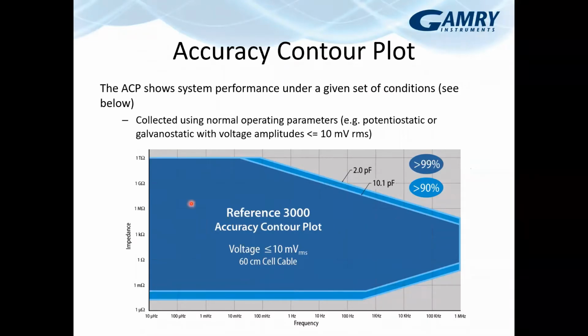When you're looking at this, you can see the impedance range and bandwidth over here at various frequencies. When you get down to very low frequencies, you're at hardware limits. The high end limit up here has to do with the low current range, the lowest current that the system can accurately measure. It's also coupled with things like system noise.